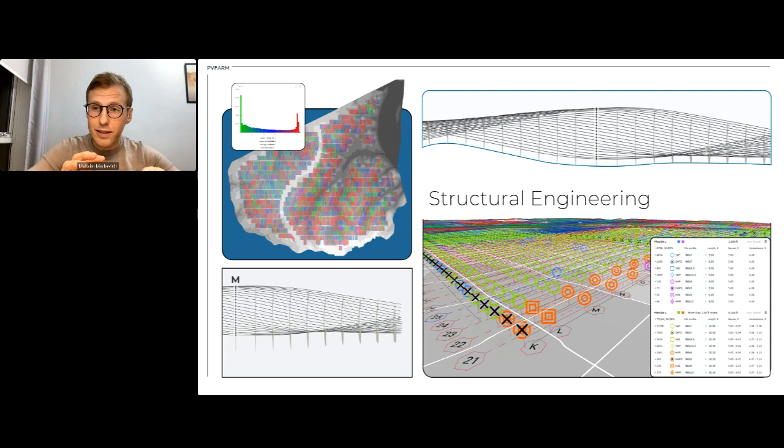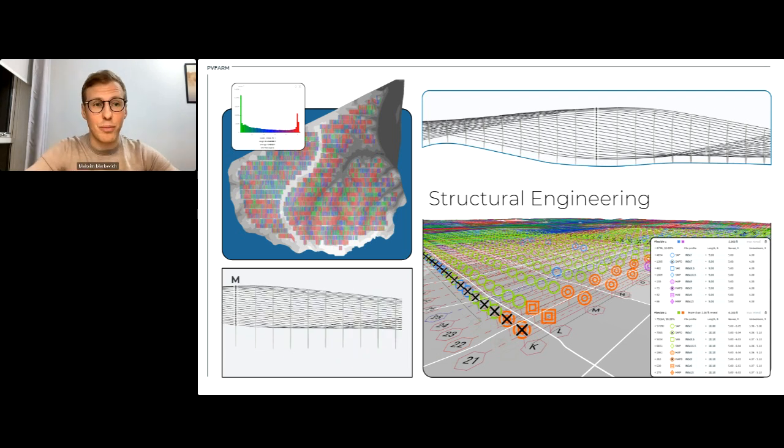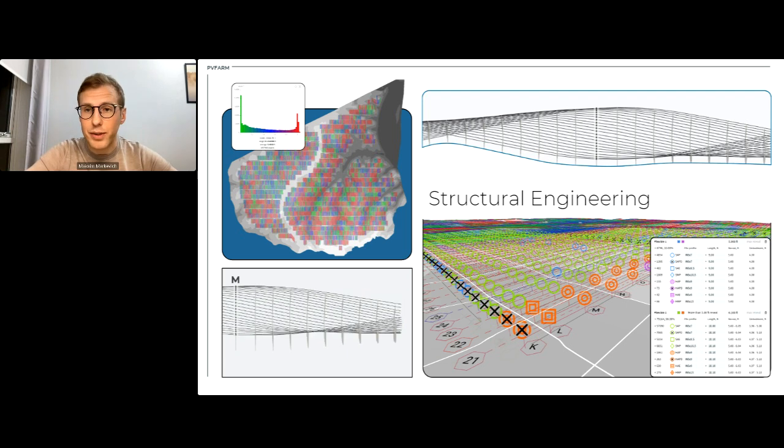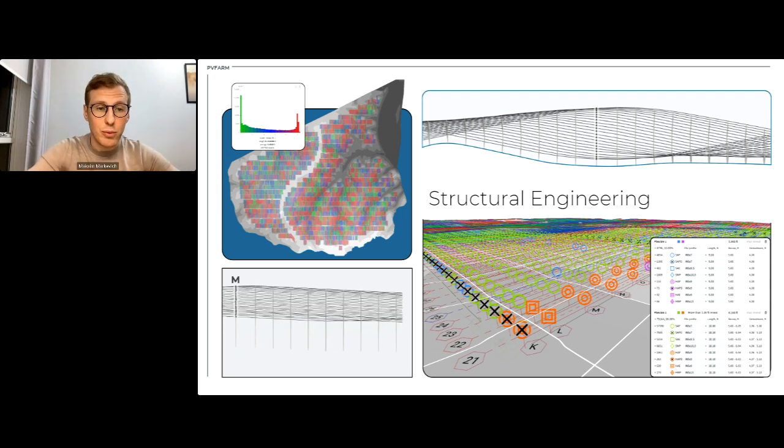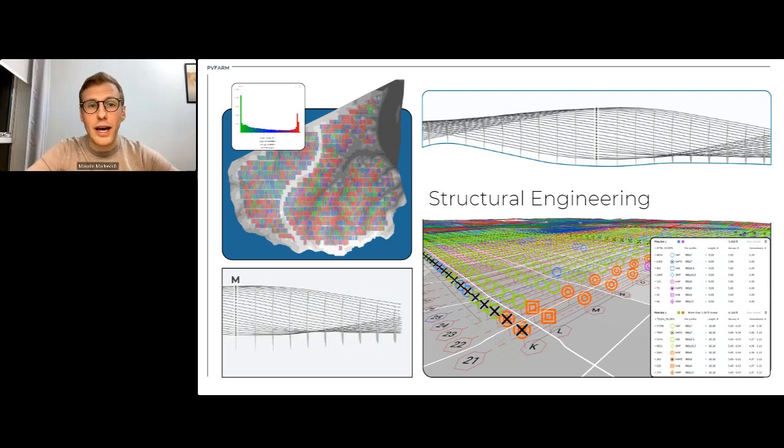So the next hidden aspect, and I would say this is the most hidden, and piles are probably the most overlooked aspect of the solar layout design. The reason is that people usually say, okay, we don't place trackers here because we have lots of gradient. But quite often it's not the dirt movements that define expensive areas. Quite often piles define it. And that's why piles are the most overlooked aspect.